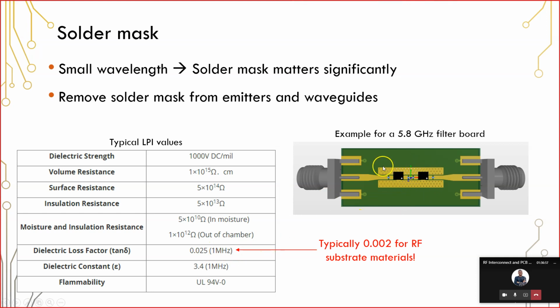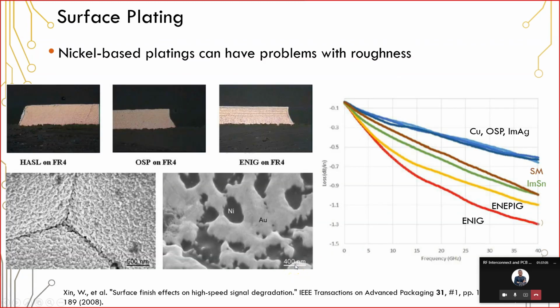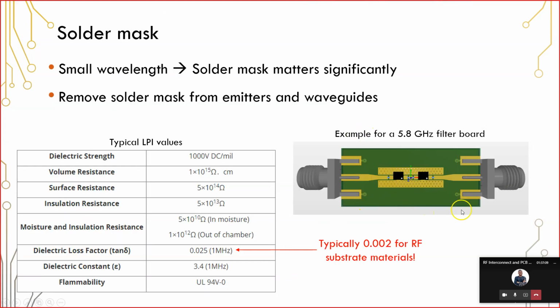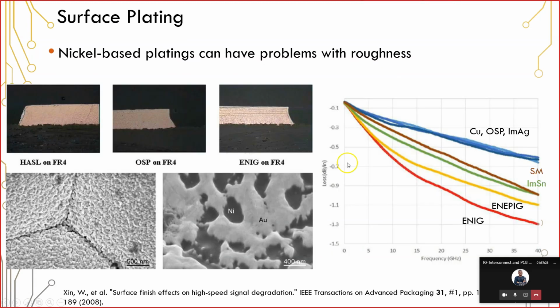But because the solder mask is pulled off, we need to ensure that all of this copper is protected and that it doesn't oxidize over time. So to do that, we apply a surface plating. And so even though you don't see it in this example from Altium Designer, when it's fabricated, it will have surface plating. And this particular design was fabricated with silver surface plating. So it didn't actually appear kind of this gold color like you see in the 3D image.